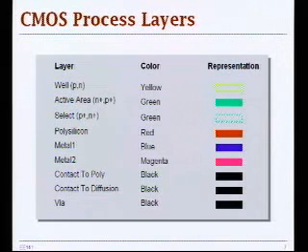And as we saw in the previous class, these look pretty complicated. You have metals running on top of each other, and then you have these vias. So it's a pretty complicated structure. So you should try to do as much as possible in one metal layer before you really need to escape to higher metal layers, because that's where you have your circuit optimized for speed. You minimize your parasitic resistance and other parasitic effects.